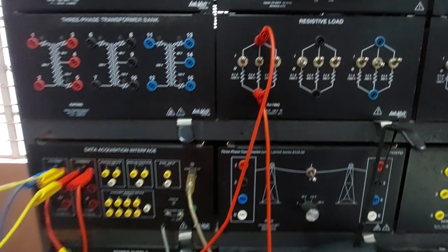So as you can see, our voltmeter in our data acquisition interface is connected to the negative terminal of our ammeter, and its negative terminal is connected to the neutral of the source in order to measure the voltage of our load. Next, our ammeter is connected in series with our load. Since the positive terminal of our source is connected to the positive terminal of our ammeter, its negative terminal is connected directly to the load. Take note that an ammeter is always connected in series.